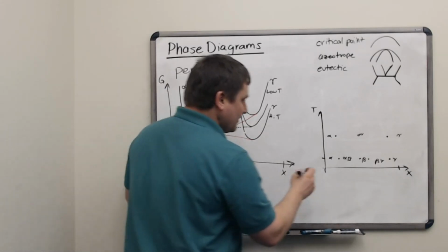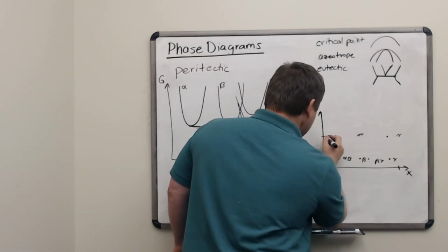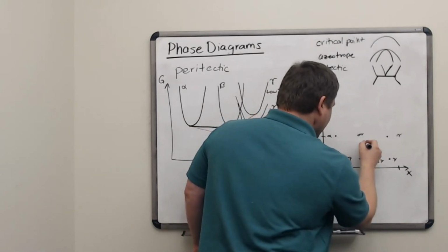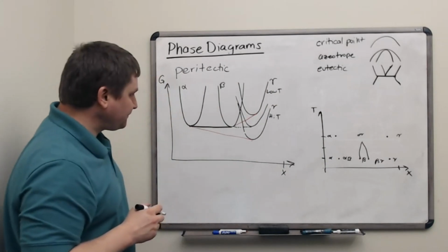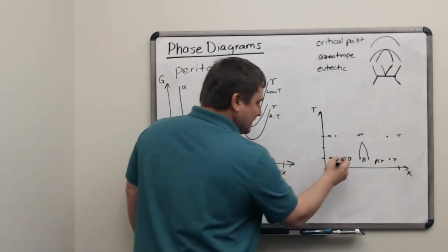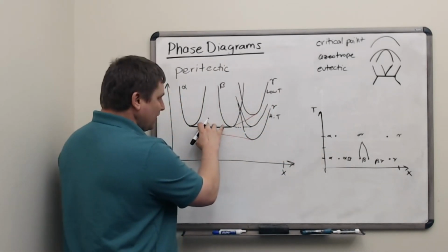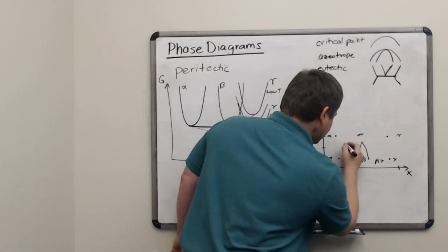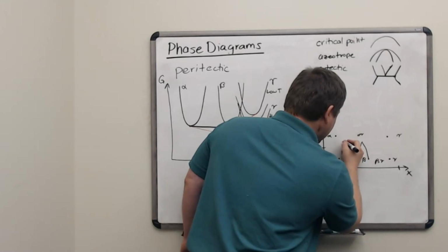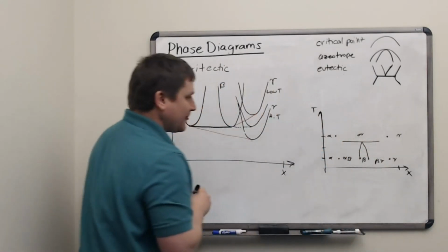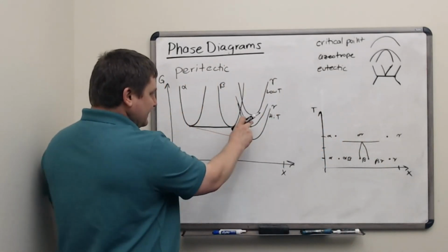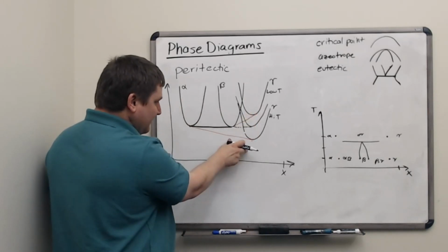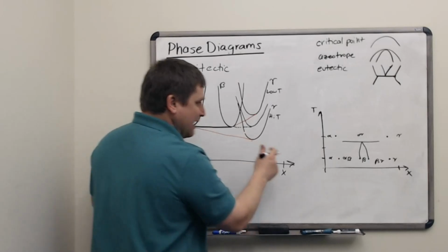So what we'll see here is a certain critical temperature where this beta peak just vanishes like that. And instantly, the alpha beta mixture that was there before turns into an alpha gamma mixture. So we've got a horizontal line here like that. And instantly at the same temperature, this beta gamma line that might have been there before gets lifted off into a purely alpha to gamma line.